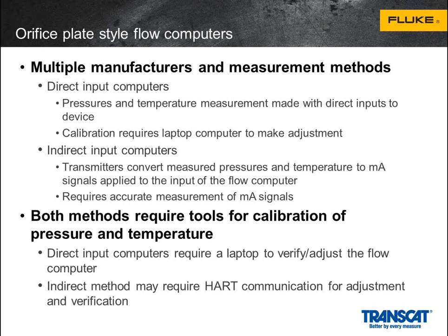There is a fairly large installed base of indirect input computers that convert those measurements into a milliamp signal. The milliamp signal is what's fed into the flow computer, and therefore you require an accurate measurement of your milliamp signals. The other thing about the indirect method is that it's not uncommon to see ones that require HART. So if you need HART, you need to either bring a HART communicator like an Emerson 475, or have a unit that can at least communicate HART and do the work that needs to be done for you.